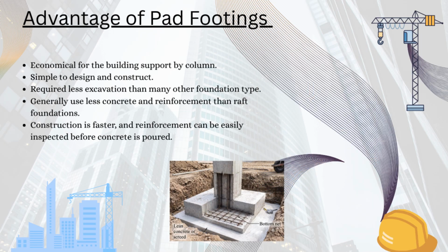Now let's look at some of the advantages of pad footings. They are economical for buildings supported by columns. They are simple to design and construct. They require less excavation than many other foundation types. They generally use less concrete and reinforcement than raft foundations. Construction is faster, and reinforcement can be easily inspected before concrete is poured.